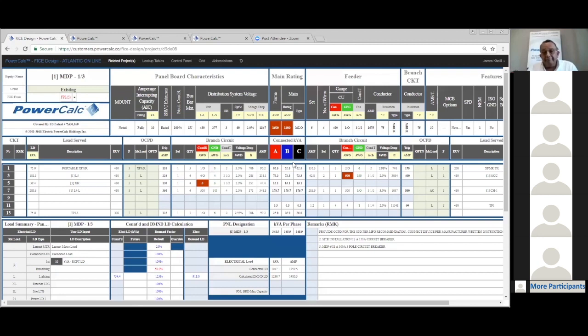And in my almost 40 years of experience in this city, I've never designed a facility that had all the transformers be the same size. So that kind of raised the flag. As I dug deeply into the design, we discovered that yes, it was designed by, I guess, another software which doesn't use the bottom-up approach. They use the top-down approach, where you set up the values of your panel, the values of your transformers, and then you start loading the panel, and hope to God that you're not going to exceed that value.